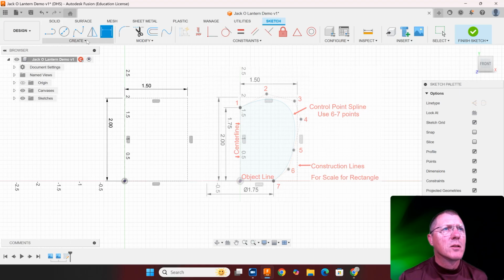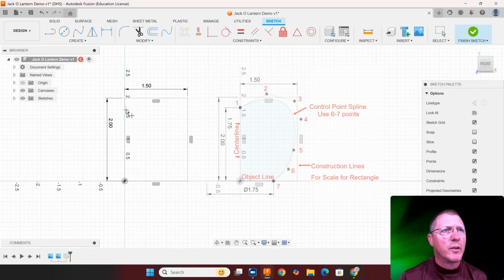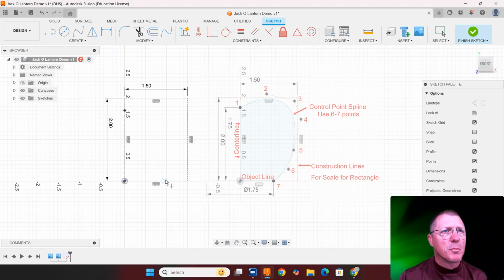And then let's go ahead and grab the point tool and let's put 2 points in. Initially, I'm just going to eyeball. I want to make sure I get the blue X that shows that, hey, you're on the line. I want to put a point eyeballed up there. And when I'm doing this, make sure that you do not select a midpoint because then you will not be able to change it. So I'm going to just come over a little ways, make sure I have the blue X, and click on the line.